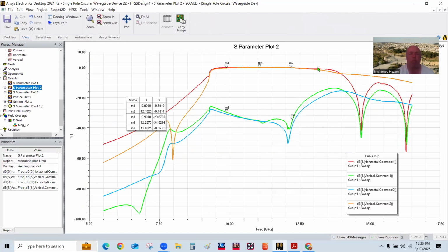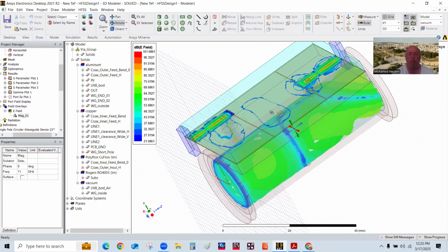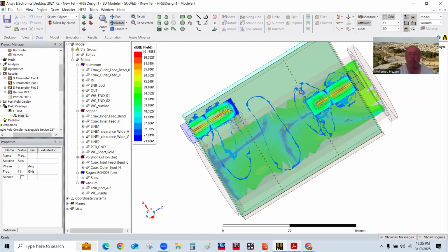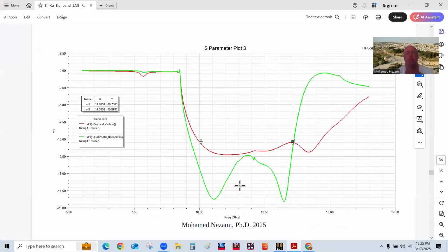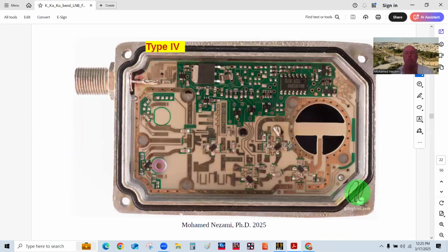Okay, you can see that this one has more rejection, and that's because they share the board and there is no housing. That's why in a lot of these designs, when you're designing these, you really have to make sure, if you look at these people that did this, you can see how they put a lot of ground via stitching and compartments. In this case, they turn it either on or off.